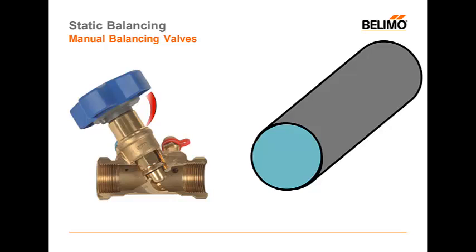When the system is balanced, the balancing valve is closed, and as the balancing valve gets further and further away from the open position, it creates a smaller area through which the same amount of water needs to pass. And this is what creates your pressure loss. In order to push water through a smaller area, we have to use energy, and in this case, the energy is water pressure. So pressure is lost as we push what should be 100% of water that in a fully open pipe through a restricted area, and this is what creates the pressure loss, which is the desired effect of a balancing valve, to consume some of the excess pressure in the loop.